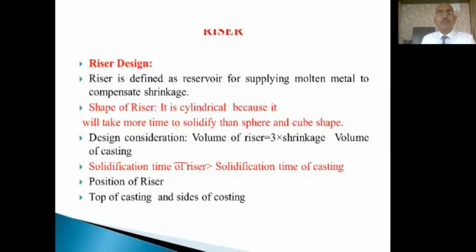Riser design. So, a very nice sentence you please remember: a riser is defined as the reservoir for supplying the molten metal to compensate for shrinkage. Generally, whatever riser shape you give while designing, it is always kept cylindrical.